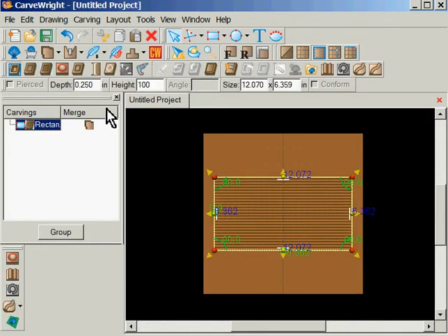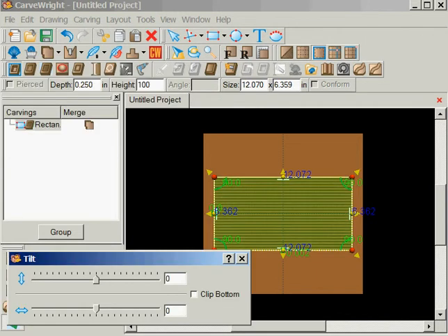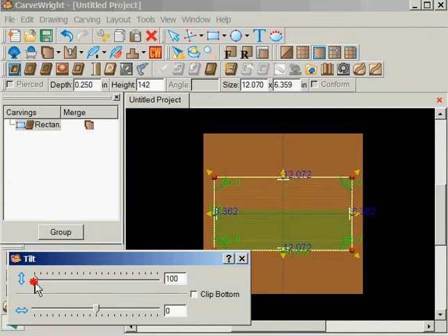Okay, so now let's go to the tilt tool. Basically, it's going to work similar to what the dome does, but it will not be a rounded type of figure. It will be a linear, top to bottom straight line, 0 to 255, 256 type arrangement. I'm going to run this over to the left side, which means that the top should be thicker than the bottom.